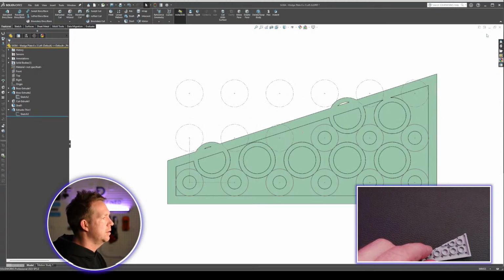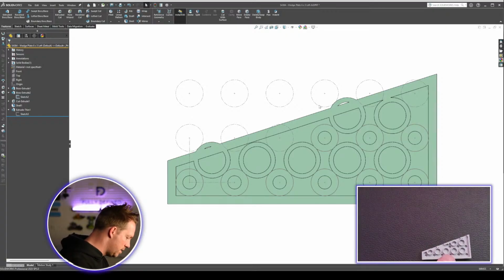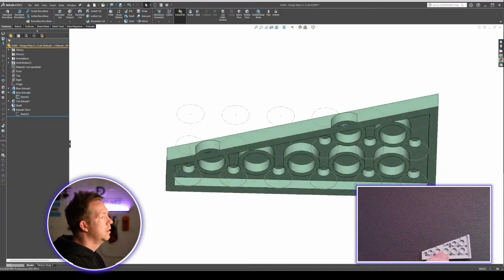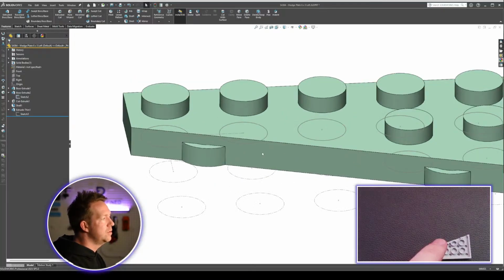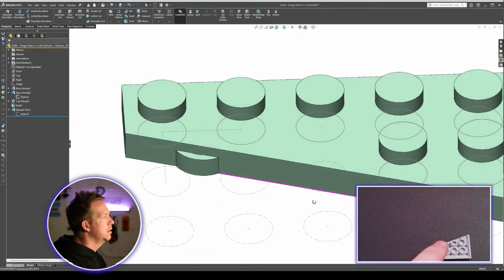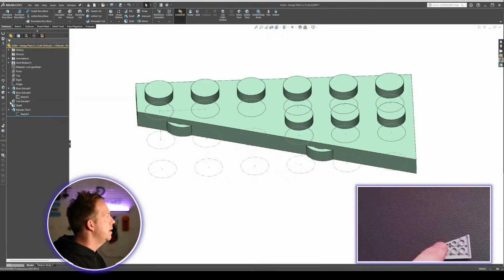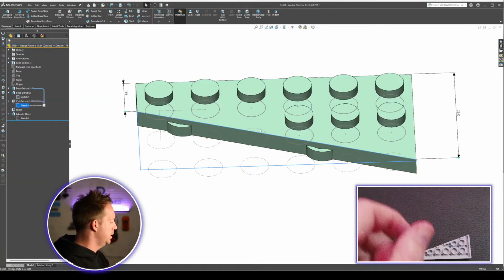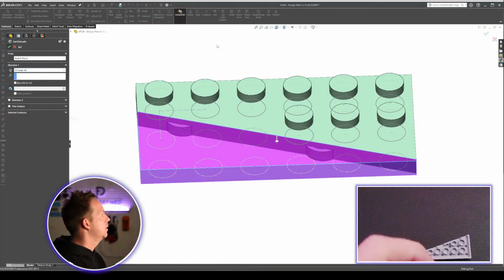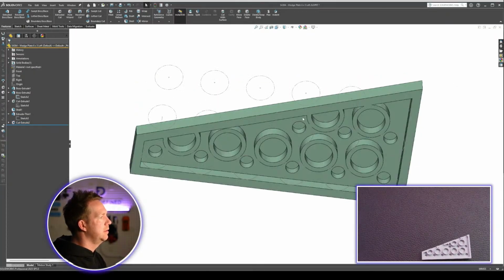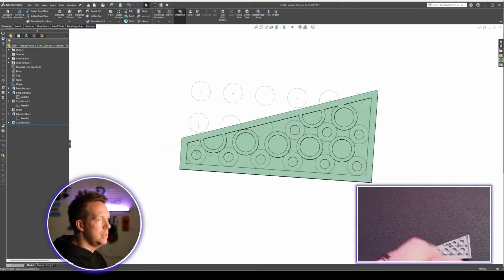I'm going to press OK on this extrude thin. We've got some detail sitting on the outside. Let's clean that up quickly. There's a few ways of doing that. One easy way is to grab this cut extrude and just redo it. So grab it again, press OK, cut down. That cuts it off for me. That was nice and easy.